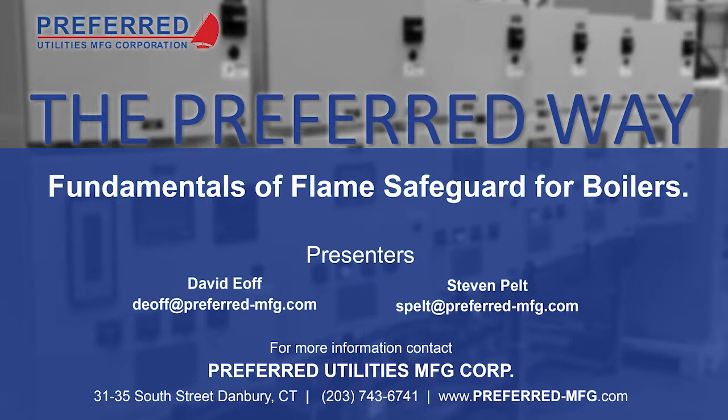Exactly. Okay, what are the advantages of systems that combine flame safeguard and fuel air ratio control, and are there any drawbacks? Well, the advantages of having it all in one go back to the size of the real estate in the cabinet. It's also one component that you're troubleshooting instead of trying to determine which component could be causing the actual issue. When it's all combined into one unit, the device is checking everything, so it becomes easier to troubleshoot a lot of the time. As far as drawbacks, there's really not that many, other than if you do have to replace the device, you are replacing the whole thing. That's basically it.